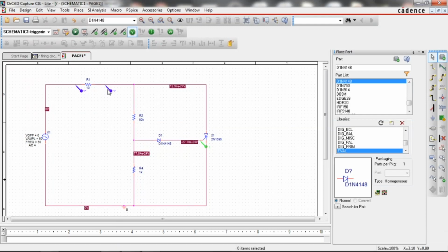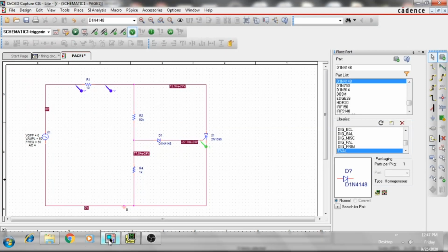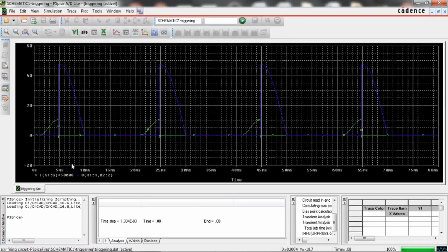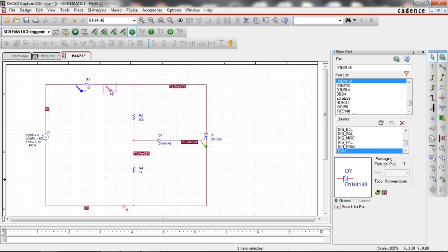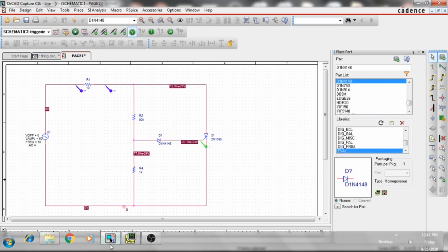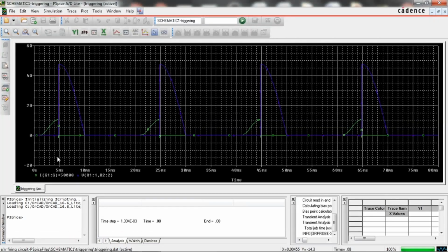Okay, can I move this firing angle till 90 degrees? We have moved here. See, whatever 60K I am using here, what is the firing angle? Okay, I can show you now. You will understand what the firing angle means. The moment the current reaches that minimum value, or the moment the SCR turns on, I can see here. I'll show this current. Yes, see, is it possible to move this beyond, now around it is 5 milliseconds?